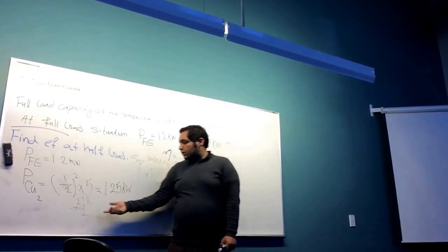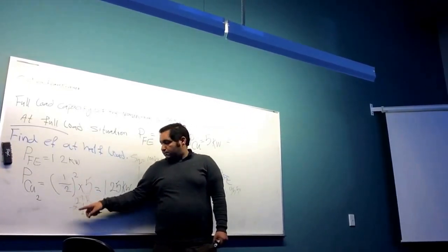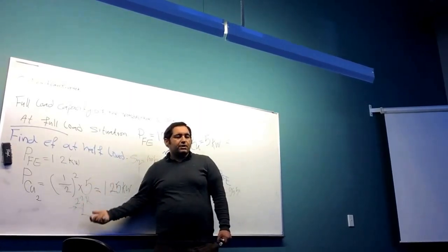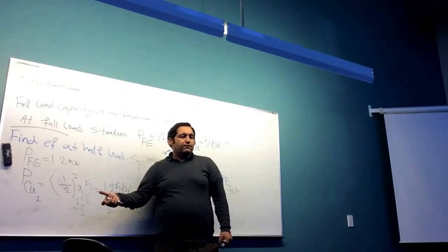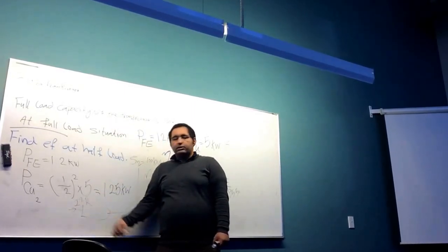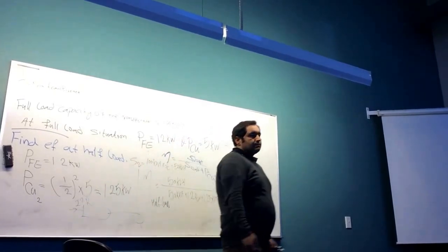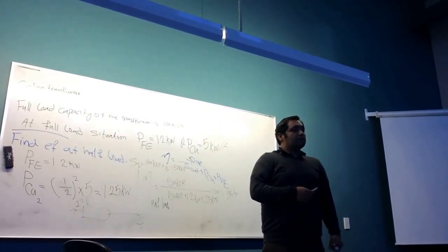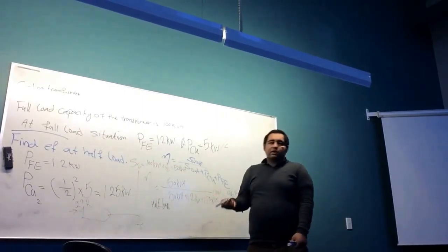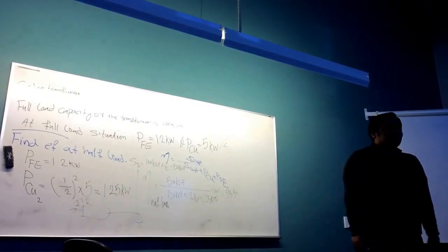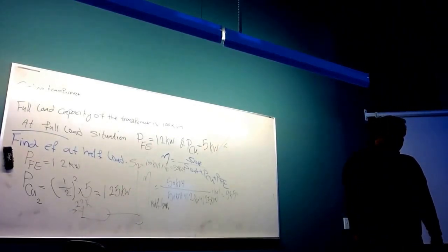Because now your current is half the current before, but remember, we have I squared times R. So if it is half, then half is squared, which is 1/4, going to be your losses. Does it make sense? Is the half change or always half? No, it's not always half. It could be quarter. It could be 1/10. It could be anything.